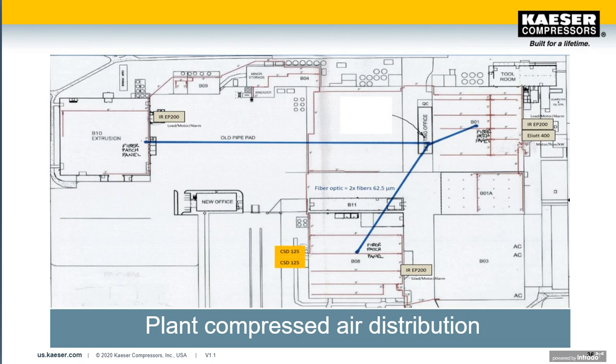Looking at the demands, with doing the study in these various areas, it was determined that it would make more sense to add the 2 new 125 horsepower compressors, those are the yellow boxes in the middle, along with some storage in the center area rather than inside the main compressor room on the top right. So instead of doing a huge piping job to distribute all the flow, with the new supply, we produce a minimum supply for each site.